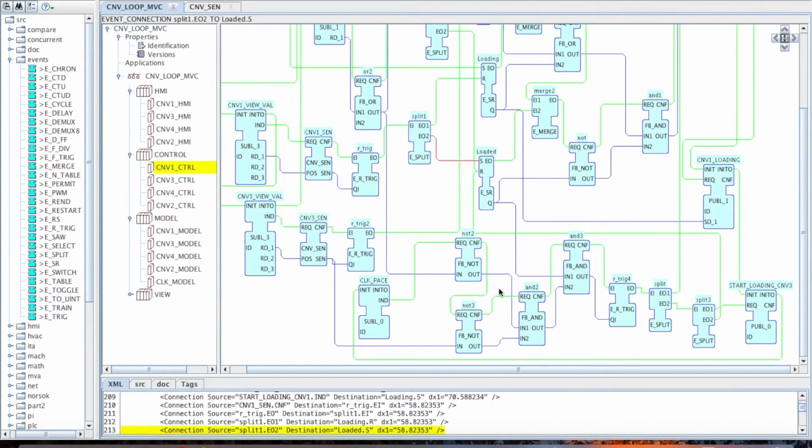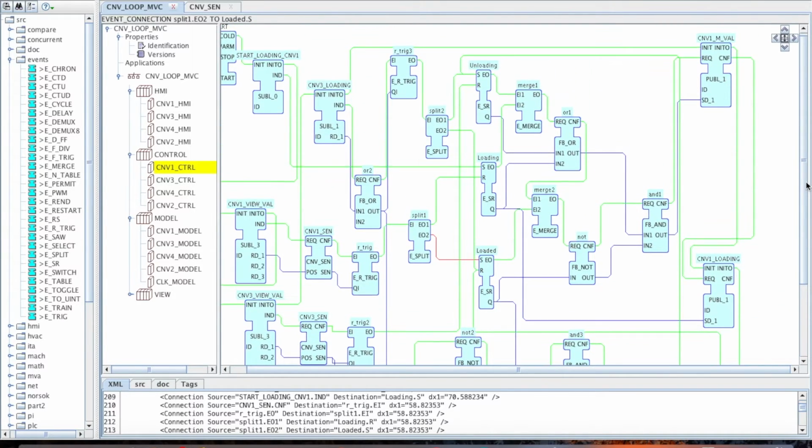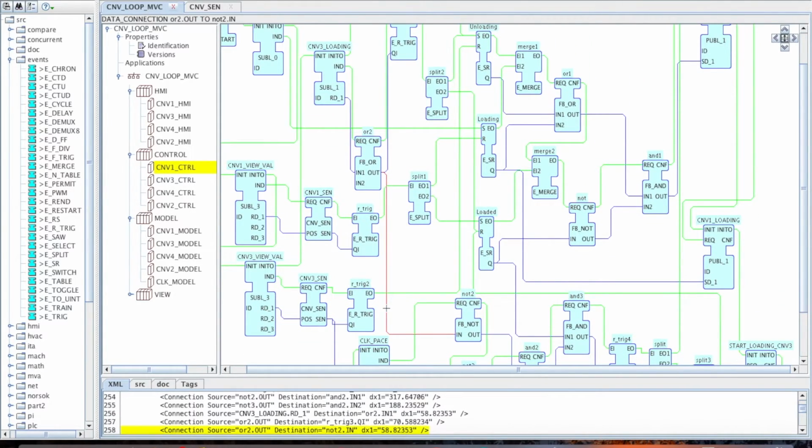And how do we push, or what is the logic for integration? Well, first of all, there are two blocks checking a sensor for the next conveyor. Let me check myself. Yes, if the next conveyor is currently loading, there is another block, a subscription block to the next conveyor, to see whether it is loading. So at the same level, conveyor 1 would be telling its previous conveyor, which is conveyor 2, if it is loading.